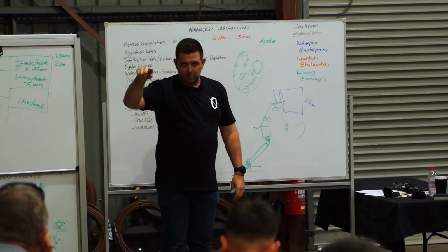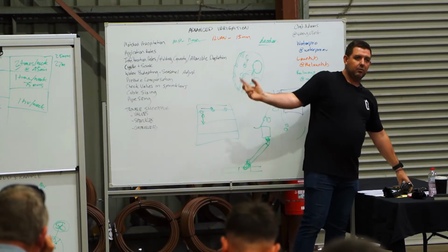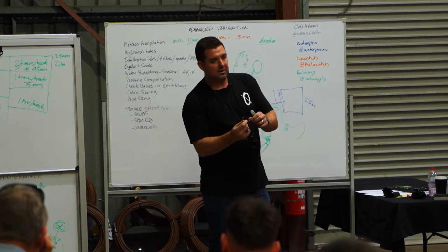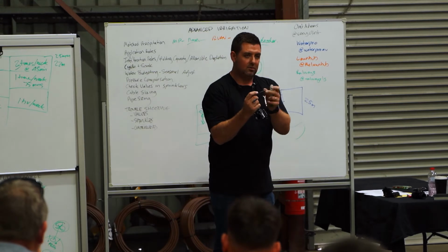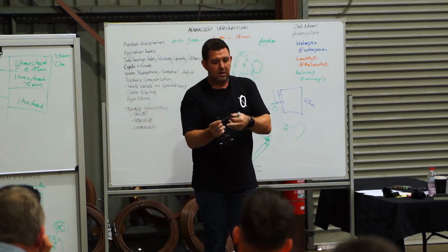Those common cables are wired up to one valve each. So when you have electricity come through station 1, the black cables are part of the circuit going to one of these, and then the pink or the white or whatever you've chosen for station 1 goes through the other, creating a circuit. It's alternating current, so it's vibrating, lifting the pin.